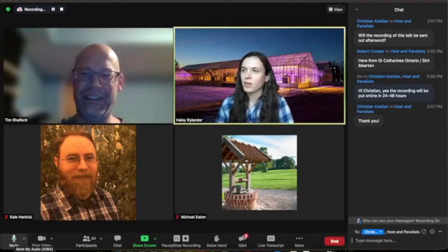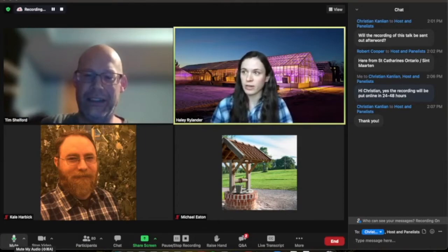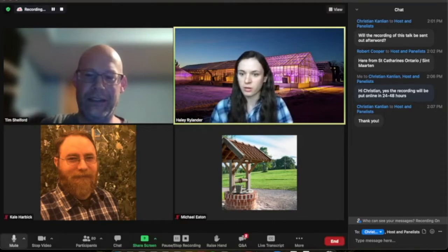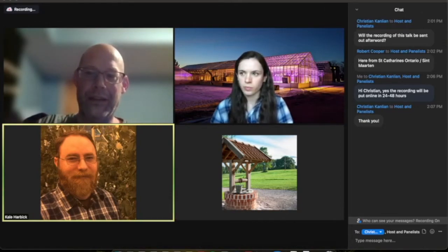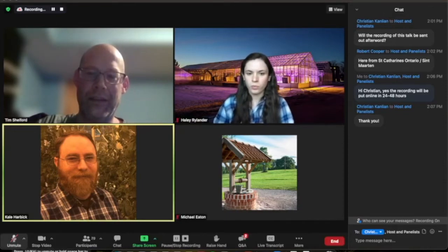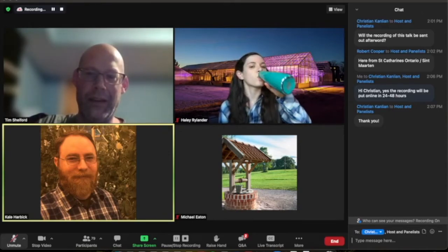Great, thank you. So from the Q&A box, thanks for your presentation, very interesting. Is CO2 gassing the only viable option for CO2 supplementation considerations? Some people do tank supplied CO2 as opposed to the off gassing of combustibles inside the space. So they're both viable. Which one is more economical depends on the CO2 prices you're able to get in your area compared with the natural gas or whatever fuel you're using, those prices.